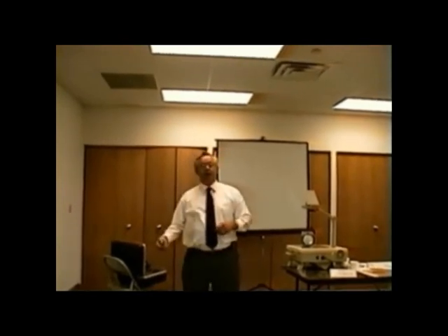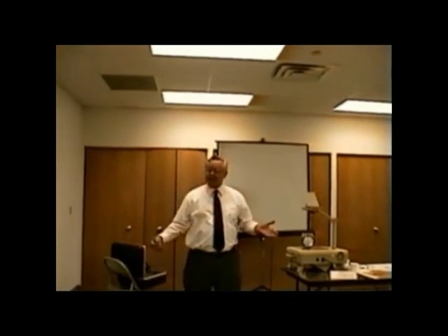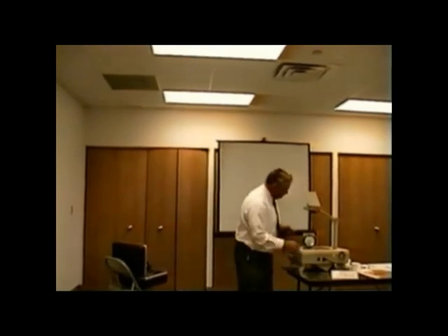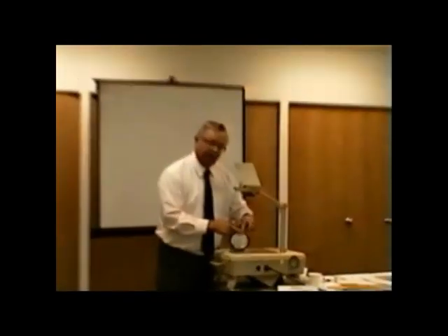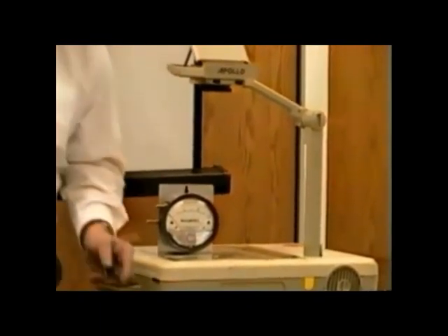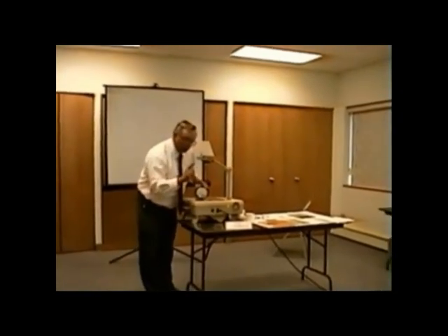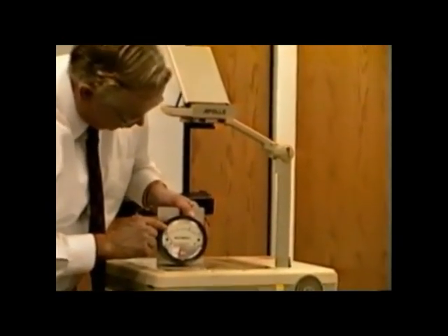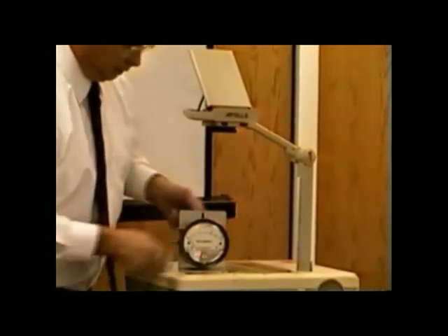Fine. Go on the other side of the furnace and poke a hole in the blower compartment. You'll get a negative reading there. That's a good reading there also. If you can't do the other way, just get a hole in there. So now, what happens is you saw that this needle deflected. When I did a positive pressure, the needle went this way. When I did a negative pressure, the needle also went this way. Positive, negative, that means they will add. Okay? So, you could read 0, 0.1, 0.2, 0.3, 0.4, 0.5, 0.6, 0.7, 0.8.